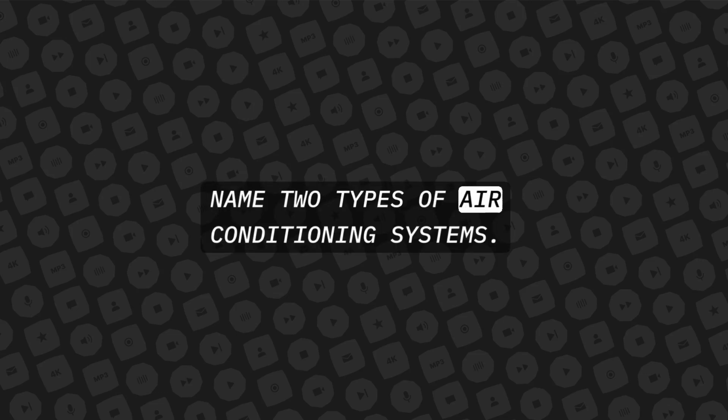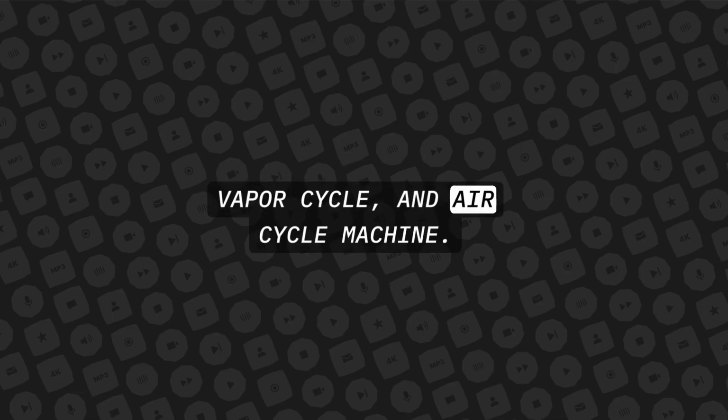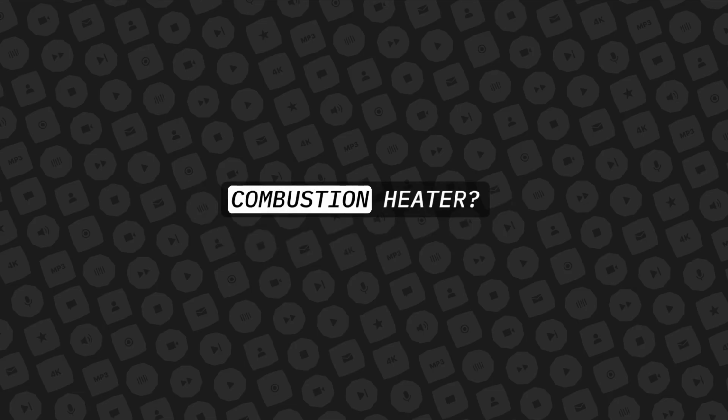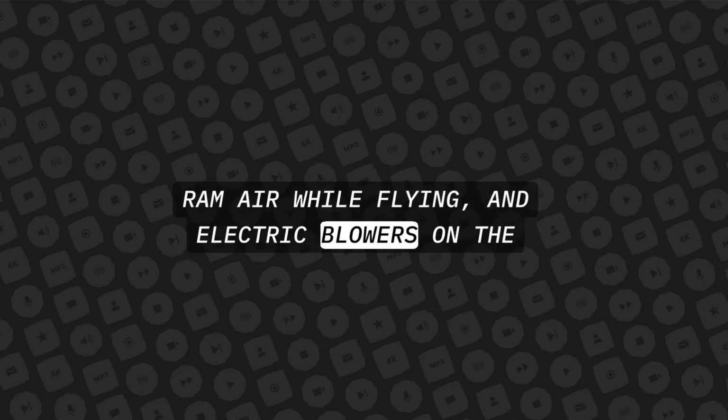Name two types of air conditioning systems. Vapor cycle and air cycle machine. What are the sources of ventilating air in a combustion heater? Ram air while flying and electric blowers on the ground.